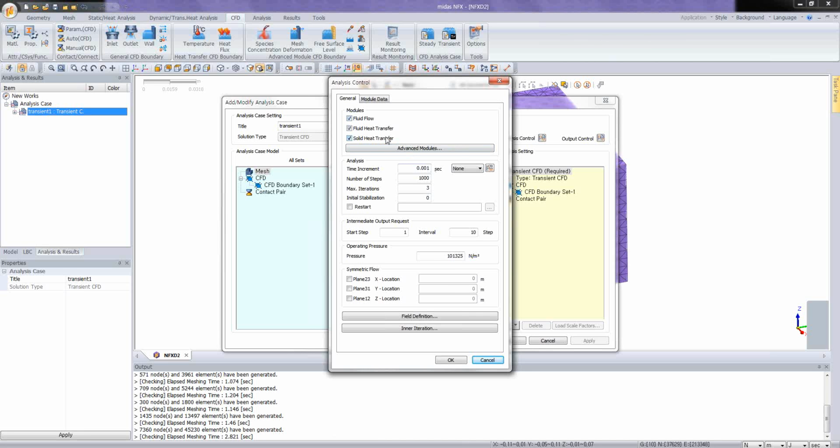But the temperature, on the contrary, doesn't need such a small time increment. So I could put 1 second if I was only analyzing the temperature. But there's a problem here. If I set it to 1 second, it will not converge because of the fluid. So I have to find a solution in order to solve this analysis in 2 steps. So this is what I'll show you.